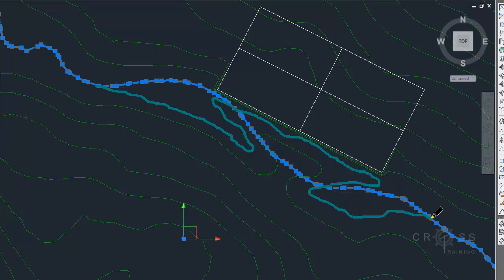And then it'll tie back to existing like that. And by doing that, my goal here, what I'm trying to do, is I'm trying to get the water to go away from the building. So when it comes down this hill, it should immediately hit this little channel here and drain out that way.